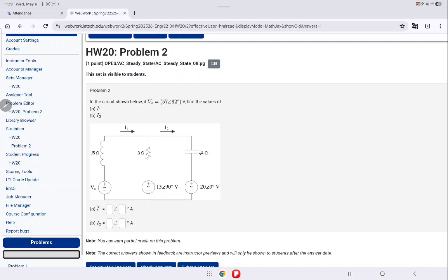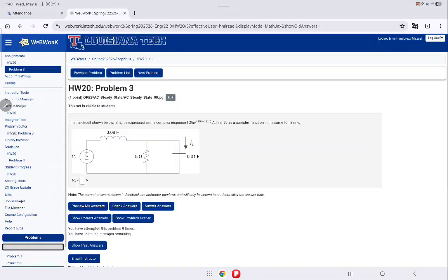No. So you can find the voltage up top. After you find that voltage, can you find I1? Yes. Vs minus that Vx that you just found divided by J5. How about I2? Vx minus 0 degree divided by negative J4. Right?